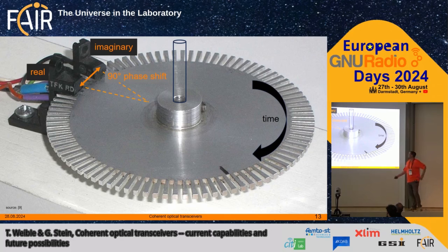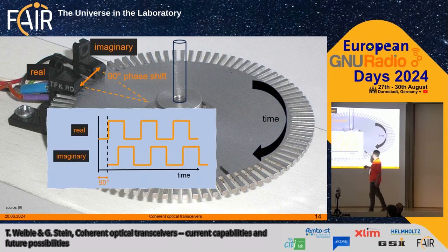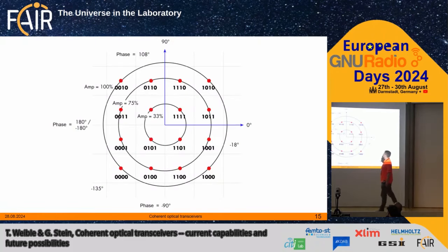The thing is, if you have phase shifting and you look at the signal, you can determine the direction. If you want to measure, for example, rotational speed, into what direction this disk is rotating, you cannot find out with just one reader. But if you get a second one and you check the pattern, which part is on one in the real and the imaginary part, and what kind of phase shifting we have, you can find this out. You can see in which direction this disk is spinning. So that's another example.